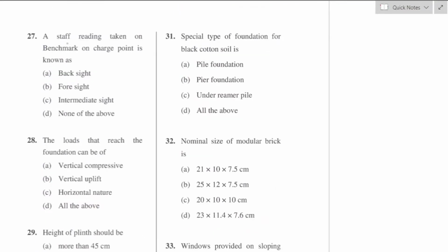Question number 27. A staff reading taken on a benchmark on a change point is known as. So when there is a change point, its staff reading on a benchmark will always be backsight. Option A is the right answer.